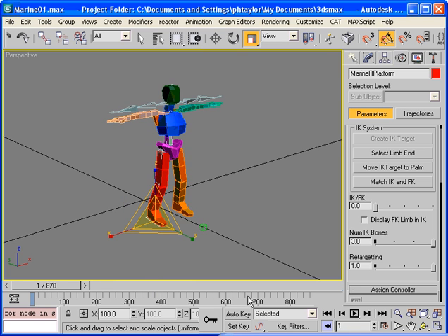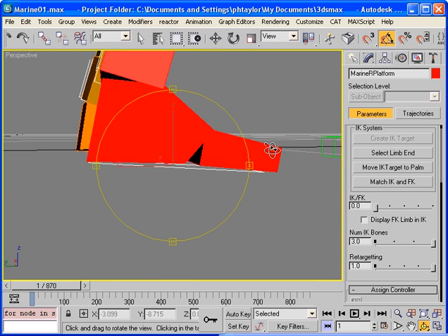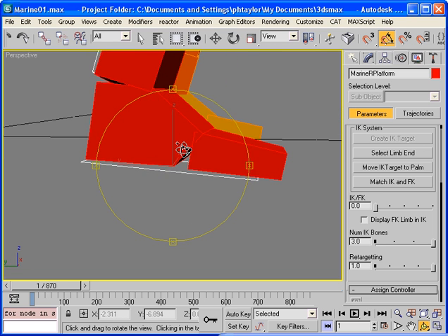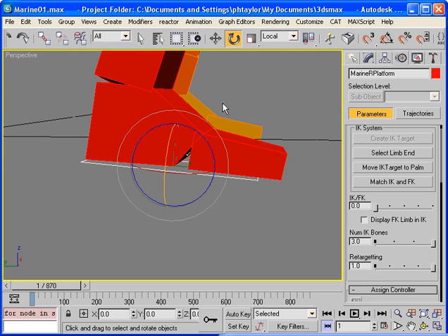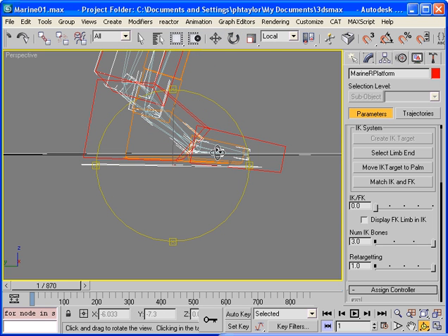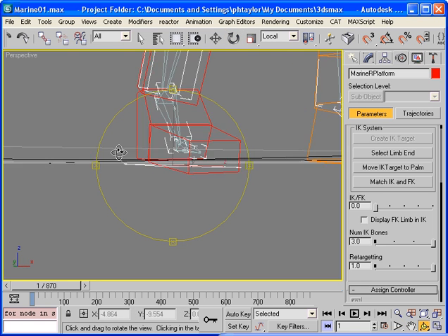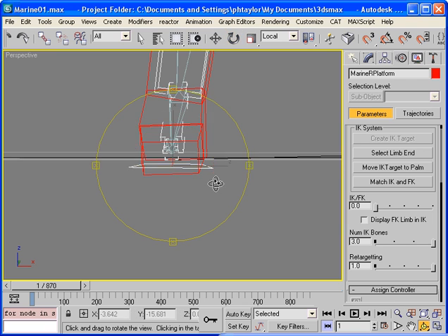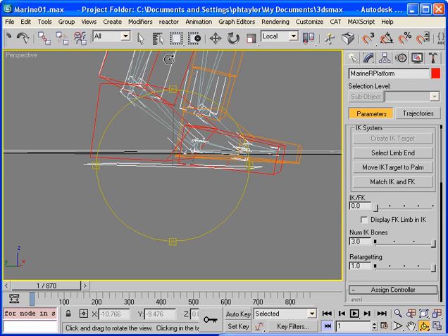First of all, the foot. The feet often need to be corrected. The ankles, we need to configure the feet to make sure they're flat on the ground. Turn off angle snaps and just rotate that foot to be flat. You can see the plane here, and rotate it on the other axis. So yeah, we also probably need to move it up.